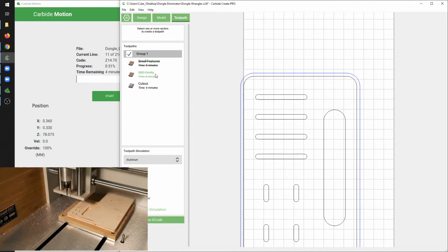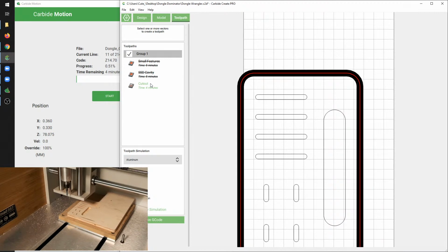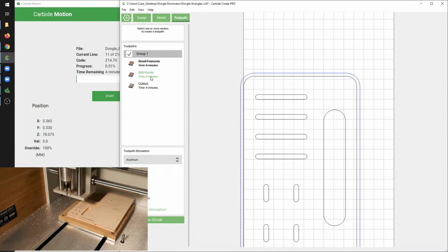It's seeing the second toolpath saying, oh, this is an 1/8 inch operation, so load the 1/8 inch tool, insert your M6 command there to prompt for a tool change. And it's seeing this, it's saying, hey, this is another 1/8 inch operation, but there was one preceding it, so we don't need to insert the M6.